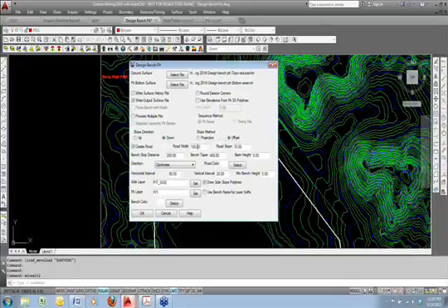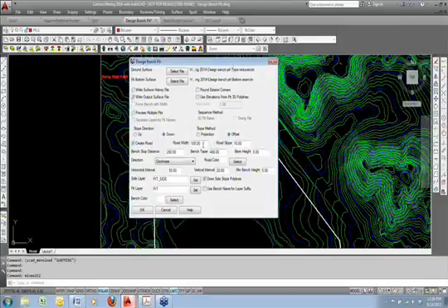And anytime you do the road or the ramp option, you have to go with the offset. That's a default. We'll put in our road width of 100, 10% slope. And here are some of the new options. It's the bench stop distance. I have it set to 200. The bench taper is 400. And these are just basically widths or lengths that you can see from plan view, and I'll show you those. The berm height, I'll just put in a 5. This is in feet or meters, 5-foot tall berm.